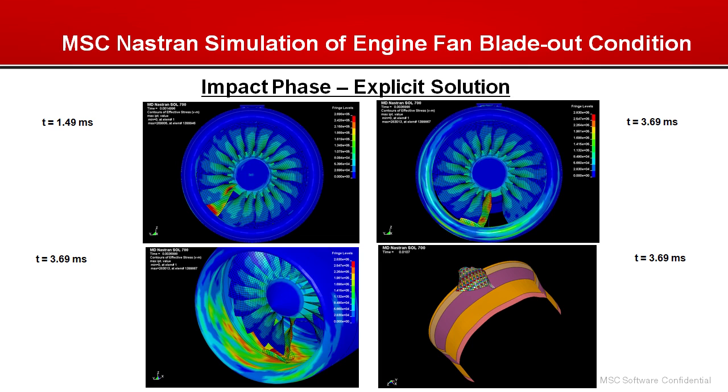The simulation computes the dynamic load and predicts the damage to the fan blades, fan case, containment, rotor, and other components, like the slides that you saw previously. Usually, the analysis is performed to capture the behavior of the engine for up to 3 revolutions. They usually do not run more than 2 or 3 revolutions.